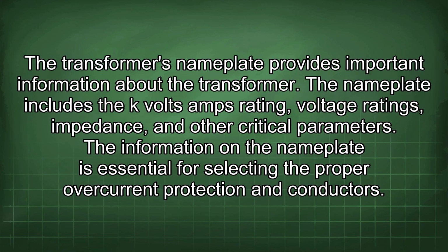The transformer's nameplate provides important information about the transformer. The nameplate includes the kVA rating, voltage ratings, impedance, and other critical parameters. The information on the nameplate is essential for selecting the proper overcurrent protection and conductors.